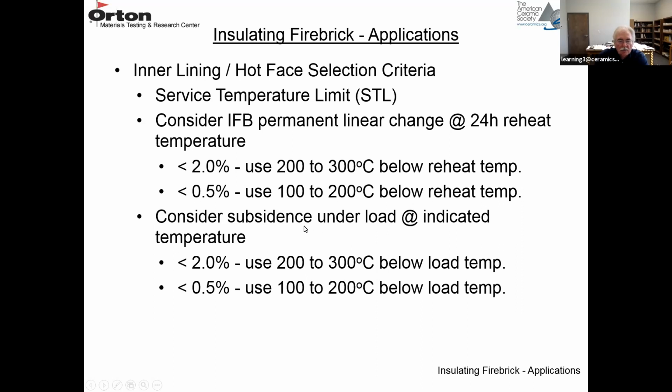Consider a RUL type test, subsidence under load, at whatever temperature the material is rated at. If it's less than 2%, again, you can use it 200 to 300 degrees C below the test temperature. Less than 0.5%, you can use it 100 to 200 degrees C below the test temperature.